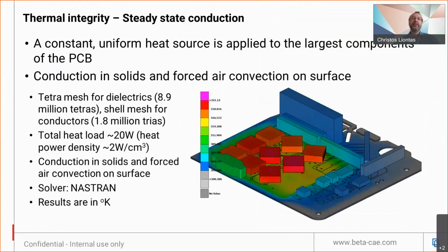So about thermal simulations, a very significant source of failure for PCBs and electronics is thermal failure because of overheating of components, and it's very important to calculate the temperature of the components. So here we have performed a steady-state conduction simulation.